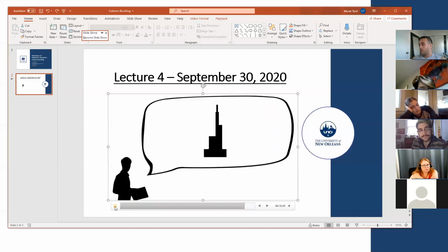This was the question that I was going to ask, but I answered the question. So when you look at the bottom, it has more area, the diameter is more, or the square footage is more. And if you look at the top, it is less. First, you reduce the applied load caused by the wind forces. Second, you need more moment of inertia to compensate the moment applied by the wind.